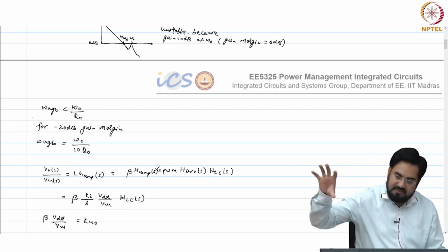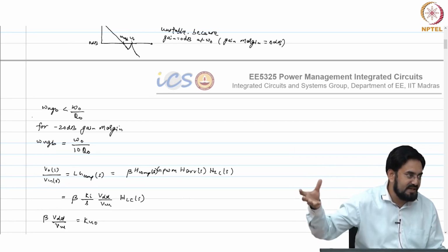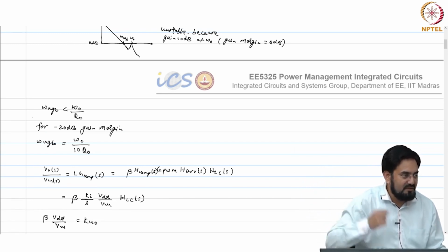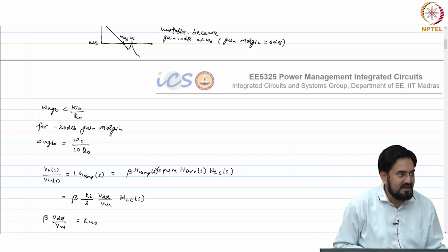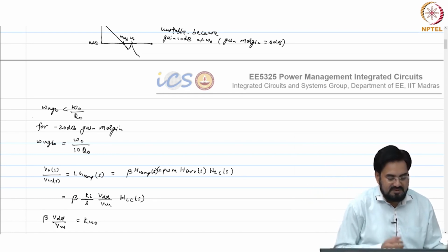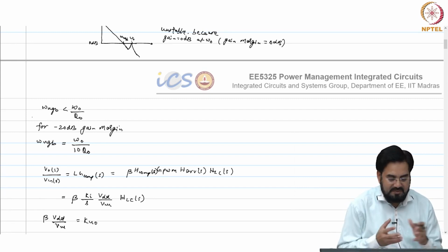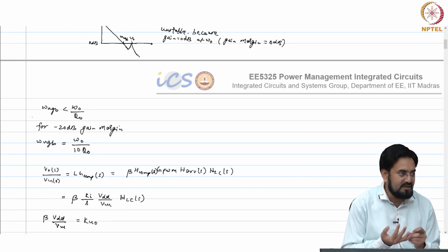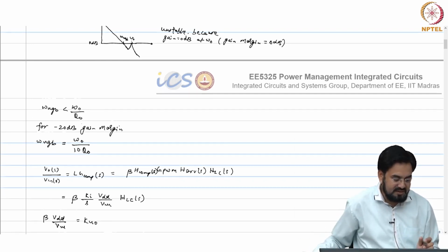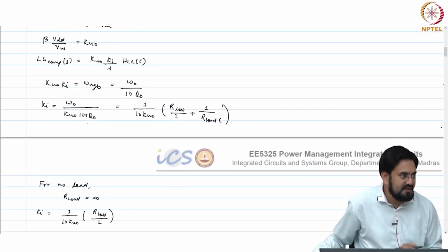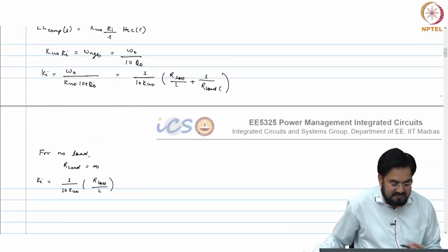So, PWM has to be replaced with the gain module, whatever the gain of that modulator is, your compensator with the transfer function, everything, and after that once you analyzed everything, you found the parameter what basically compensation parameters you require, or here it is all you need to find the value of Ki based on your specifications given.